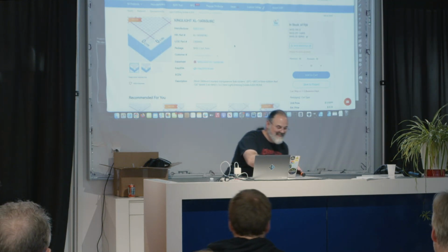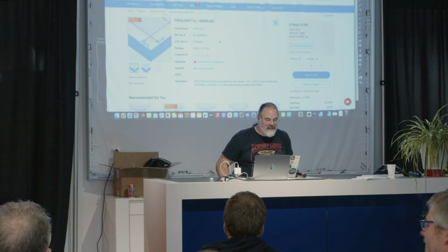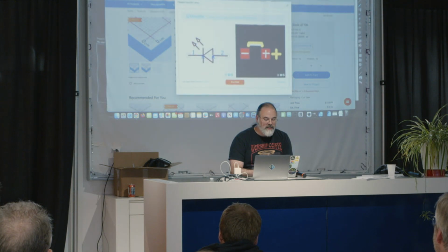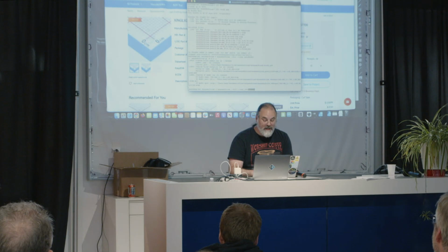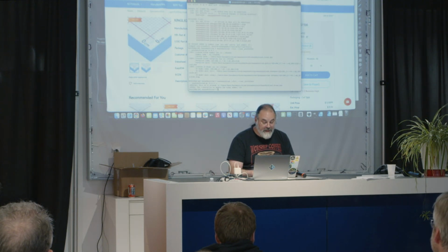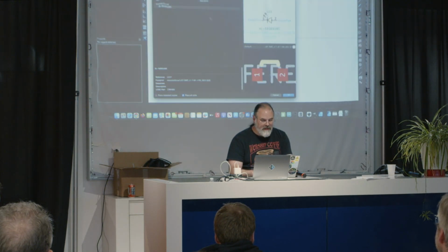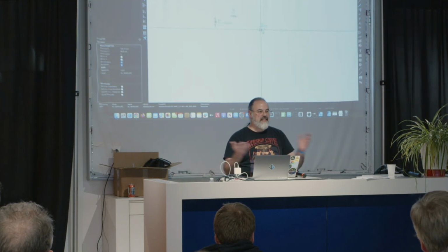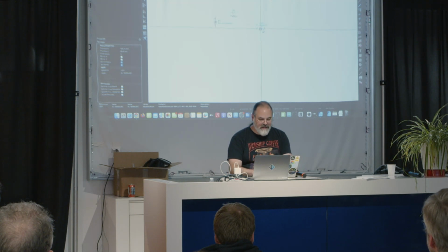That's all right. All right, so I have found a blue LED over here. I'll just copy this ID. I just make sure that EasyEDA has the schematic and stuff in here, and usually that means they've got everything. I've found a good 90% plus of their library, which is impressive, has everything. Right, so this looks like it pulled down a STEP file too, a WRL, the whole thing. So I'll go over here and I'll hit A and just paste that in, and there it is. So I didn't have to do anything really to get this in, and I love cheating like that.